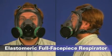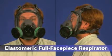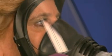This is an elastomeric full facepiece respirator. This type of respirator provides a higher level of protection than filtering facepiece and elastomeric half-facepiece respirators. Why? Because it provides a better seal to the wearer's face. Another advantage of this respirator is that it covers the wearer's eyes, protecting them from liquid splashes and chemical vapors.